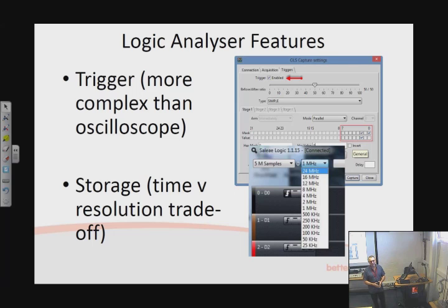Say we're looking for a particular scenario that just happens once in a while when a bug happens. We can leave the device sitting there waiting for our particular error condition to crop up, and gather the situation. And weirdly enough, it can actually look back in time, because of course it's recording all the time into a circular buffer which freezes, and so we can look at what the signal traffic was, both before and after that very special triggering event.